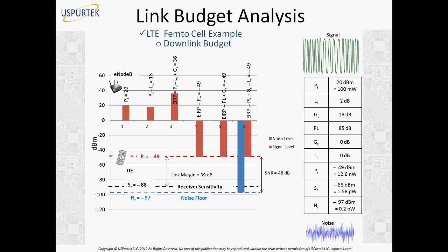So that is why femtocells are coming out as a very good solution to loss of signal inside the building. That means setting up E node Bs inside the building itself. Otherwise in a macro cell or even in a micro cell, your E node B might be outside somewhere, right? I mean, E node B could be housed in a building, but the antenna on the E node B might be outside the building. But in this case, both the antenna and the E node B are in one single box. It just looks like a wireless LAN router, and you could put it anywhere inside the building.